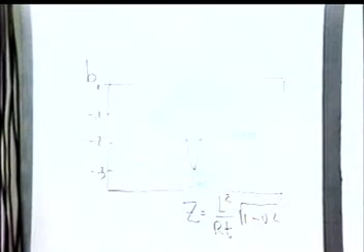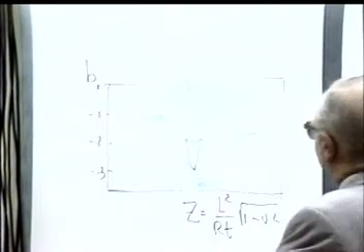You may also want, in that paper of yours, to find the lengths at which the coincidence of the eigenvalues is perfect, not up to the fifth digit or fourth digit. Because you were increasing the length, and you had eigenvalues more spread out, so you can decrease the length a bit and find some critical lengths, and you see what happens. And then when you find that length, maybe you will be surprised. Why do you have such a big imperfection sensitivity there? Because you will get even steeper.